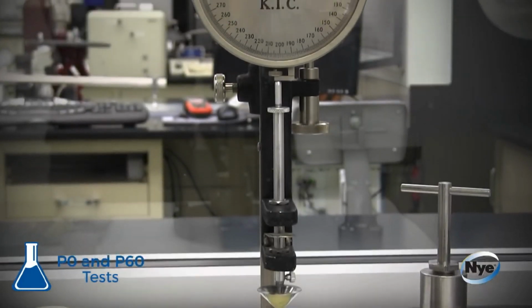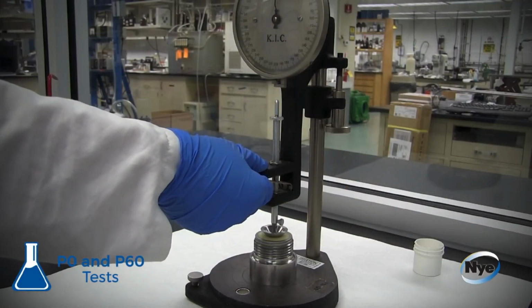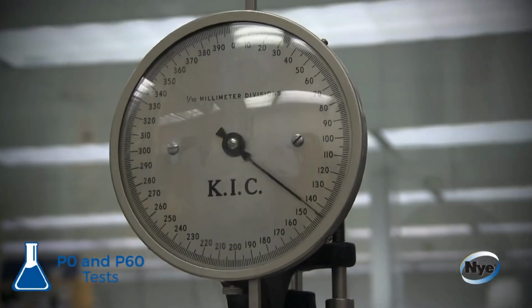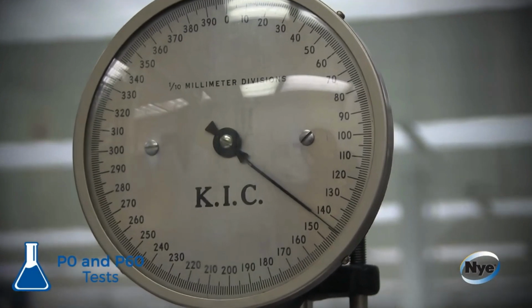Okay, this is the device. That's where the measurement's going to come up. You saw the cone dropping into the cup. You saw it sank that far. And then they're going to pan up, show you on the gauge, 1/10 of a millimeter, and that gives you your penetration number. Anybody need to see that again? I know it's not exactly Citizen Kane, but okay.